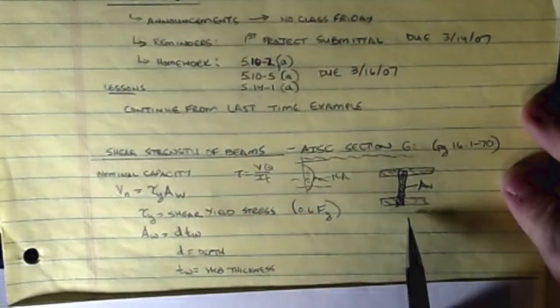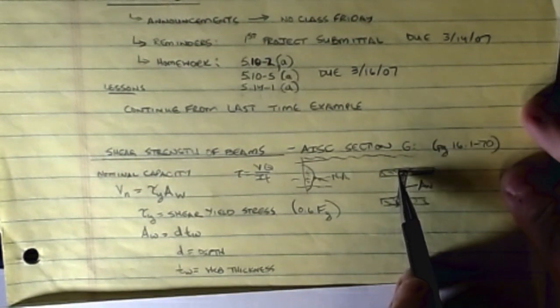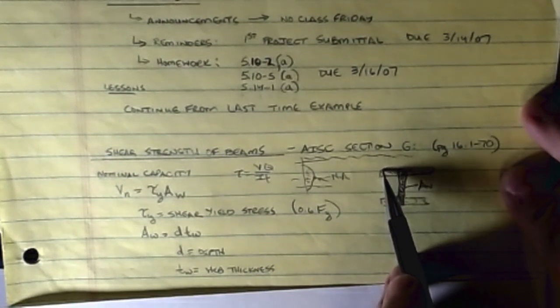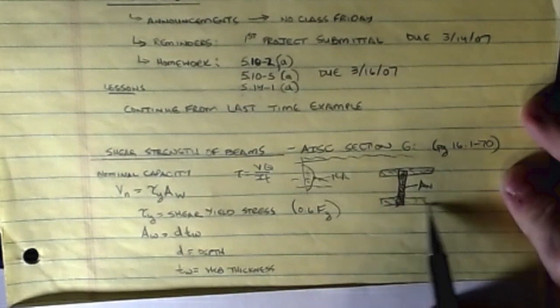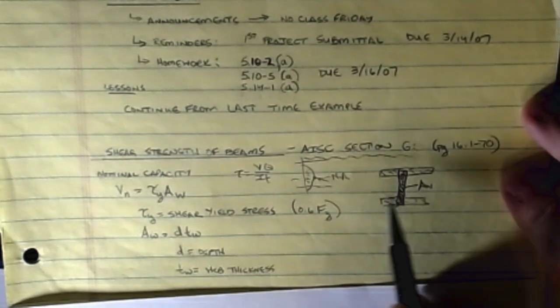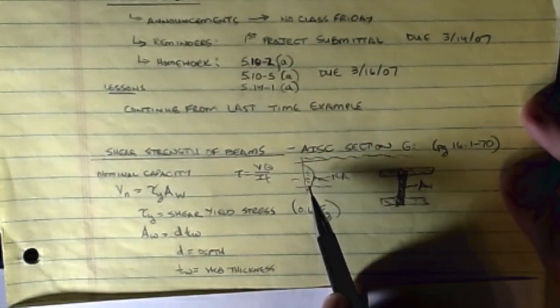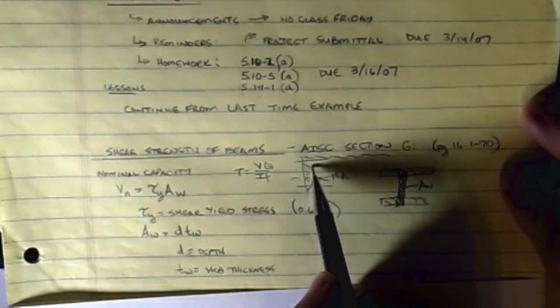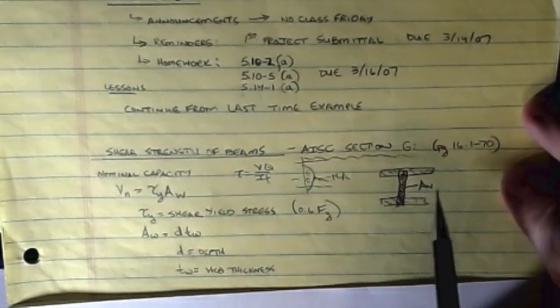It ignores the flanges. That should make sense because out at the end regions, at the top tau is 0, and at the bottom tau is 0, and tau max is located in the middle here at the web location for a doubly symmetric shape. So you're getting very little resistance in these little regions toward the ends. Most of the strength is in the web of the beam.